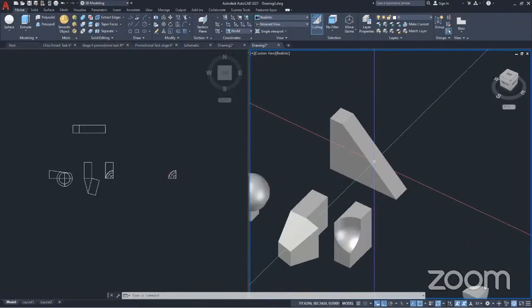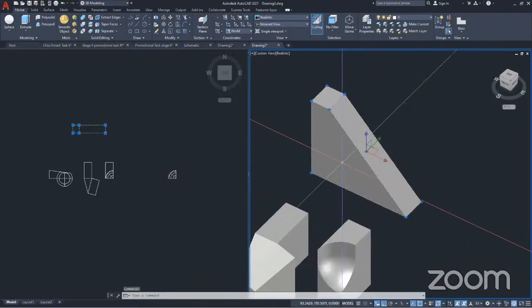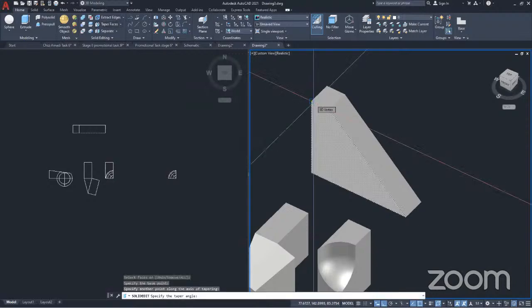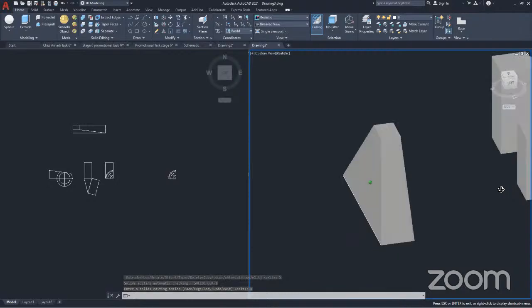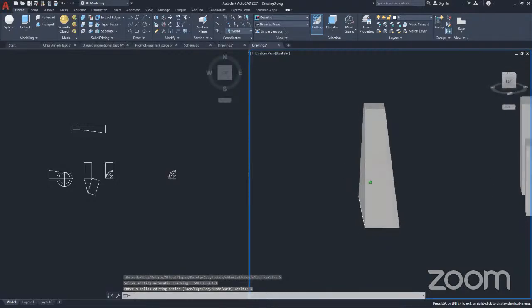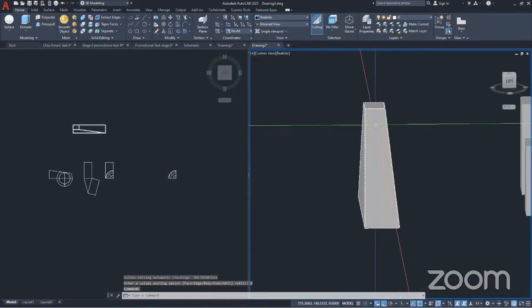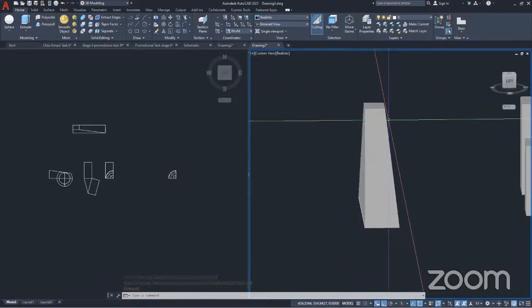Okay. Now I'll do it again. Like so, enter, specify first point, specify second point, and then 7. Enter. Okay, so that is it for tapering. So we've tapered this face. If you see the way it is, from the base, it looks like this, and then it's tapered as it goes up. That's it. Okay, you all understood it. Okay, no problem. Let's continue.